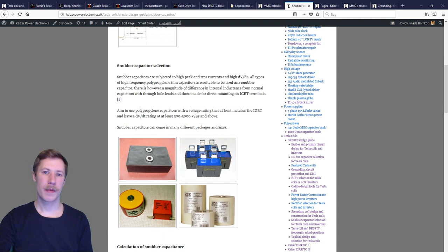These are very heavy MKP capacitors, also known as GTO, from gate turn-off capacitors. They are known by this as they were originally developed for large SCRs, or thyristors, because when they turn off in hard switching modes, the switching spike, which you will also see in IGBT inverters, the current spike induced in the inductance would give a high voltage transient. And in order to capture this and dissipate it, we use a snubber capacitor or a snubber circuit.